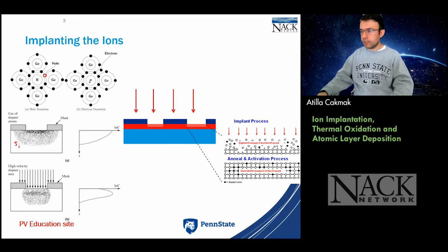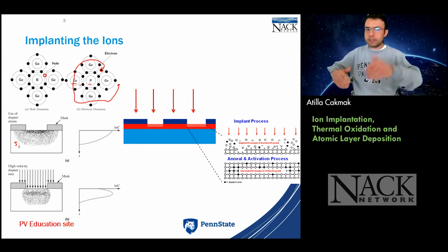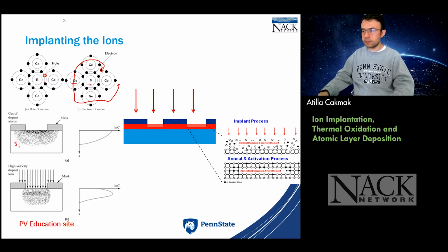If we dope it, and that's the key word, dopant, dope it not with boron, but with phosphorus, then we will have an additional electron, because that's what phosphorus is able to offer in its valence electrons. So there's going to be an additional electron that's not going to be shared here, and that's going to increase the conductivity, because this electron will be much more free to move around the crystal. When I say crystal, I mean these cascaded atoms, germanium atoms here. The hole also increases the conductivity, because now I have this absence of an electron here. Any electron will have a chance to go and invade this vacancy, and there we go. If we call conductivity electrons hopping from one location to the other, then we just established what we're looking for. The electron has moved from one side to the other, and we have conductivity in action. Great.